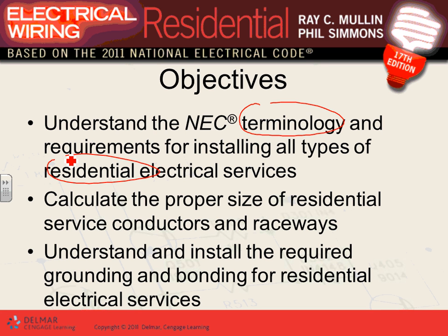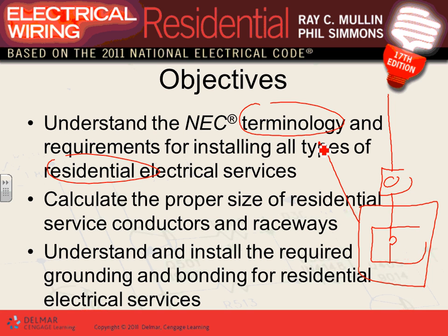Today, the focus, of course, is on residential, but all the information that we're going to be talking about in terms of service entrance equipment, aka the first panel that you have and you land your conductors into, applies to all services. But the focus, like you know, is going to be residential. Proper sizing for residential. So you brought your conductors into that meter socket, out of that meter socket into my main panel. So the whole system here, this is your service entrance equipment. That's your service entrance equipment, where you have your disconnect, your first circuit breakers, and you land your service entrance conductors right in here. That's called service entrance equipment.